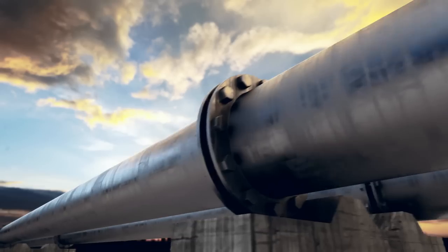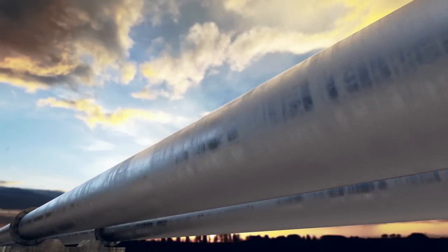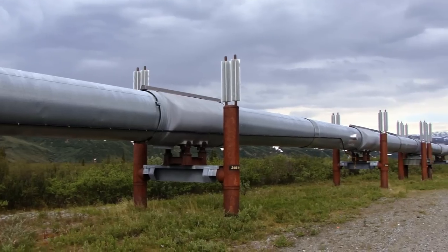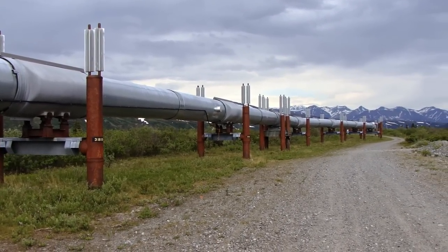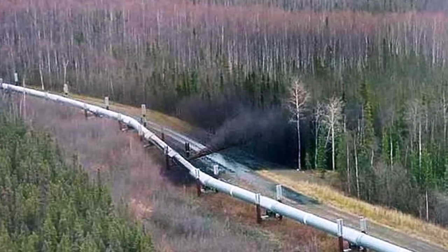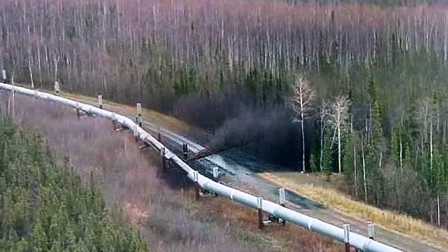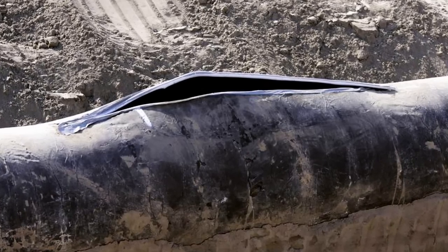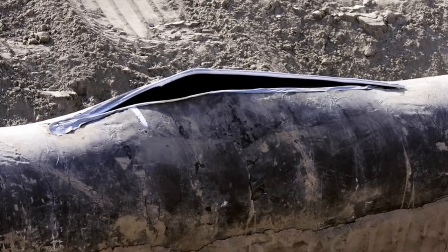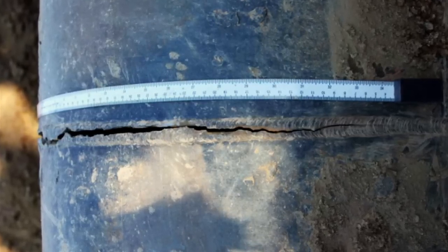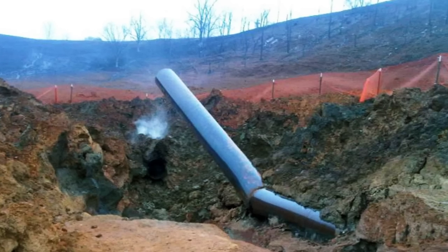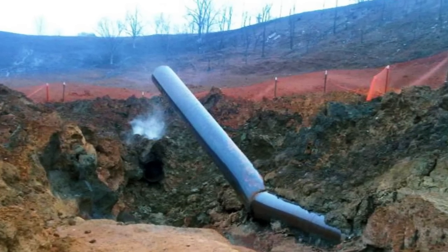The most effective way to transport large amounts of oil or natural gas over long distances remains the pipeline. In pipelines that have been in use for decades, manufacturing flaws like cold welds or hook cracks can lead to degradation through corrosion or fatigue. Assessing whether a flaw will remain stable or grow to become a serious defect is the main purpose of non-destructive testing. At Applus RTD, we recognize the importance of detecting anomalies as early as possible in order to prevent failure or shutdowns.